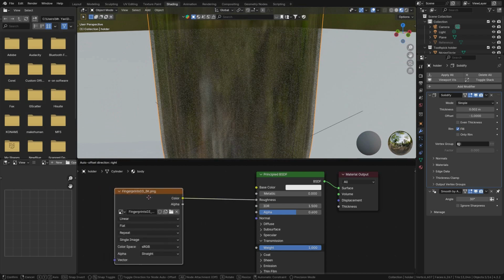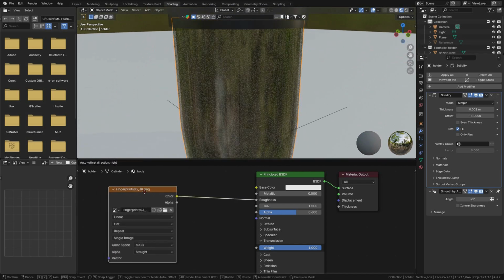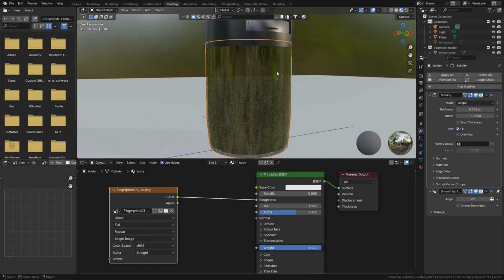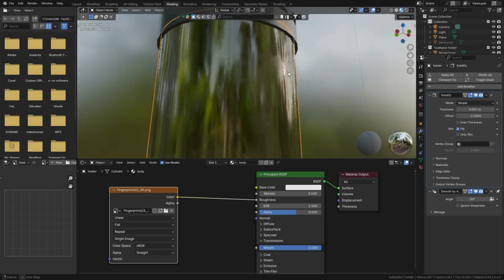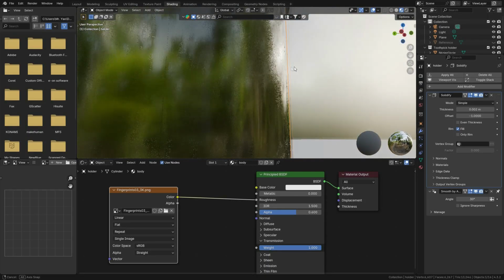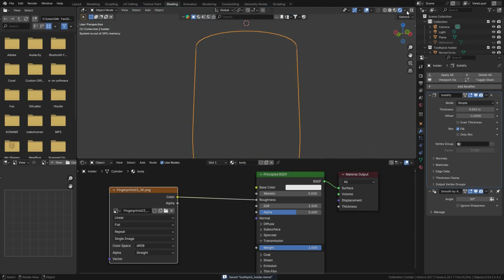The reason why that is because it's taking the black and white values and trying to mask them across this surface, which is letting us be able to see these imperfections right here. You can try going to Cycles, save my file first, go to Cycles, see system is out of GPU memory.